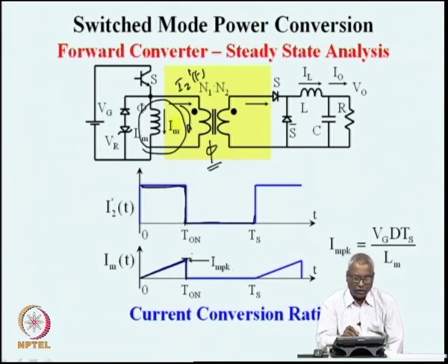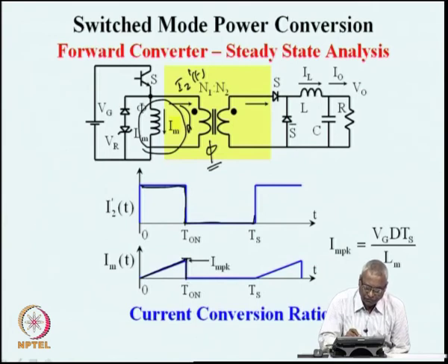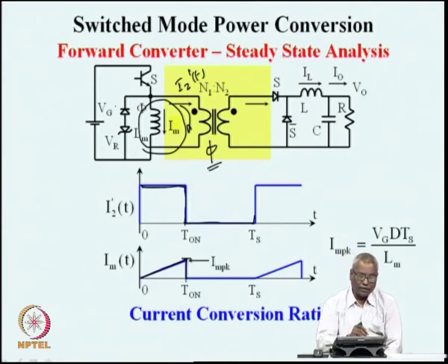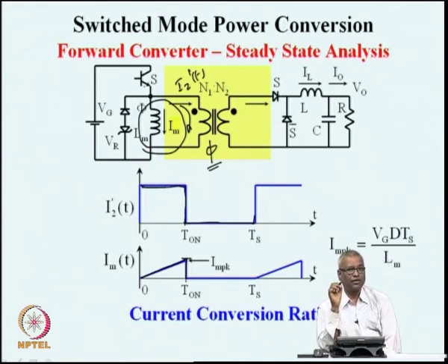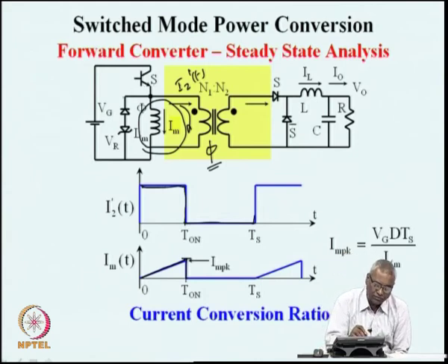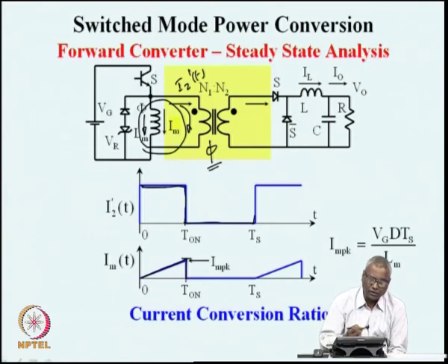the core. And then when we switch this off, this magnetizing current comes to 0, because this has been switched off. But the inductor current can never come to 0. The switch current can come to 0, because the switch has no associated stored energy. So, when this comes to 0, and if the inductor current is continuing, where does the current go?